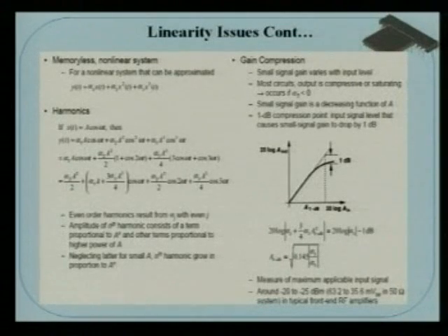That energy will be distributed to those harmonics too. This is the output at the fundamental frequency omega t, but output energy or power is shared with all other harmonics. So definitely you understand the output power will be reduced at the fundamental. So that's why it gets reduced. Now if you quantify that, how much power gets reduced? Say I say 1 dB power compression. Then 1 dB power compression is the measure of linearity.